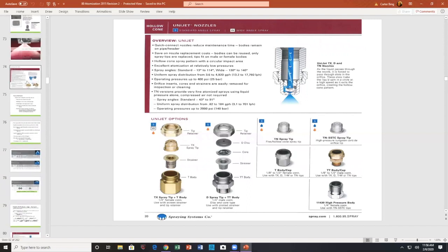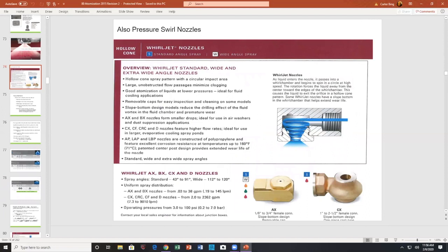Anyway, again, there's a spin in here, and the spin causes the spray to spread as it leaves. You want it in here long enough so the flow striations are balanced out, but not too long. The longer it's in there, the more pressure drop you use up. So there's an optimum length for this diameter. 2.75 times the diameter should be the length of it. It's long enough to spread out the flow striations, but not too long to waste pressure drop. Okay.